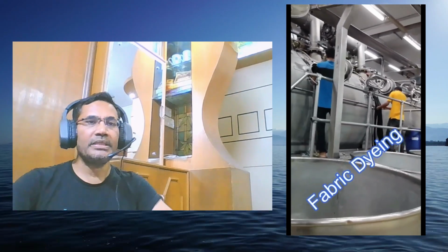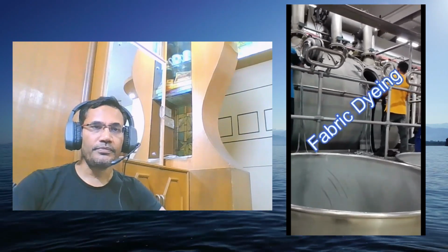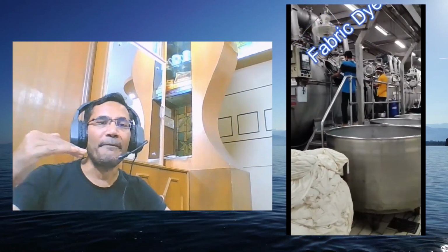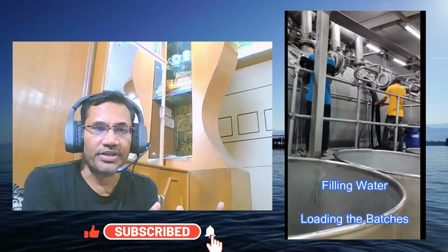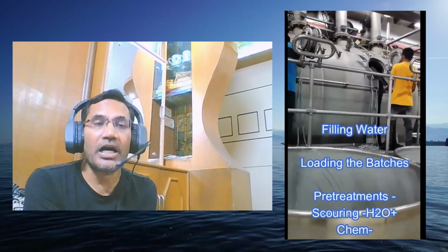These are different chambers, and how the full work is going on in these chambers, I'm sharing one by one. Just see, first of all, in this machine you have to fill up the water, then load the base, and after loading the base, there is some pre-treatment. In pre-treatment, the first part is scouring. Scouring means you have to use water, then some chemicals like sodium hydroxide and hydrogen peroxide.